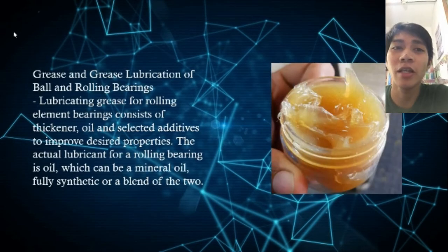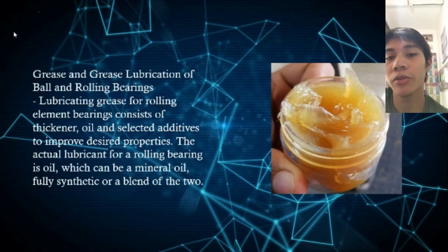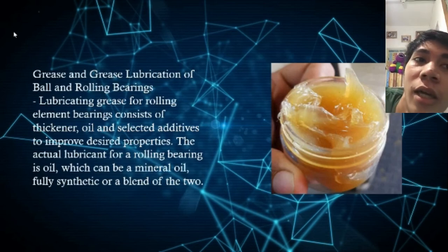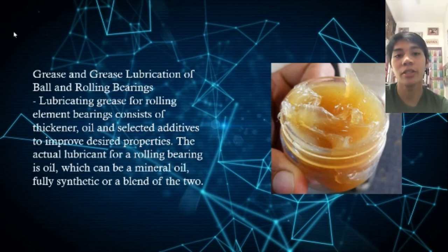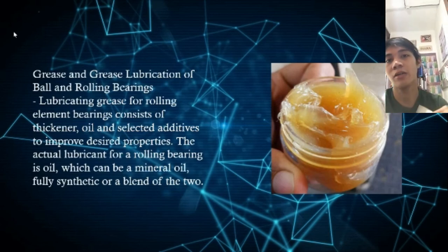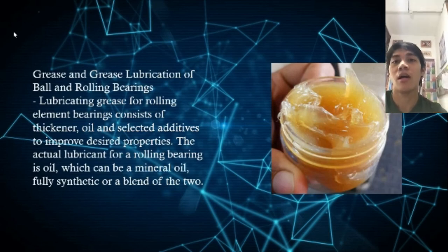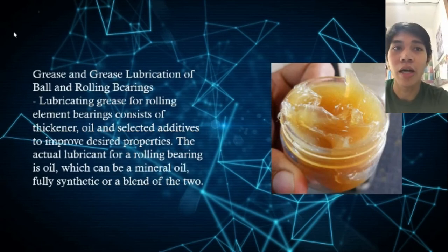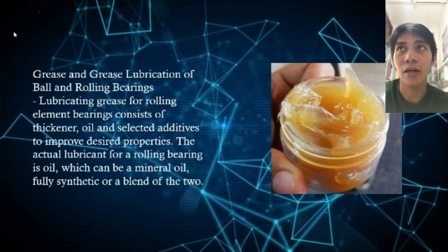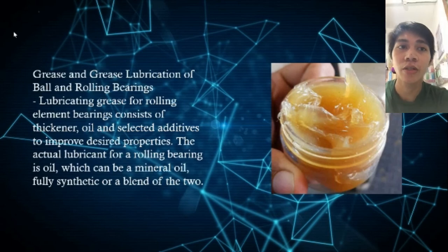Different types of additives are added to these oils to influence corrosion resistance properties, and or build layers that protect the metal surface under extreme conditions. Additives also improve the viscosity behavior at different temperatures.